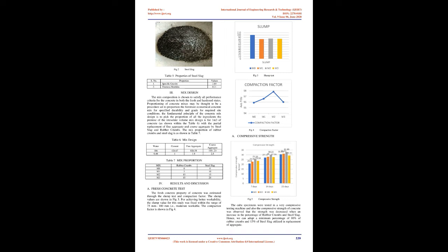C. Coarse aggregate. Aggregates are the foremost mined materials within the world. Aggregates are a component of composite materials like concrete. The combination is a reinforcement to feature strength to the general material. Thanks to the relatively high hydraulic conductivity value as compared to most soils, aggregates are widely utilized in drainage applications like foundation and French drains, septic drain fields, wall drains, and roadside edge drains. Aggregates are used as base material under foundations, roads, and railroads.